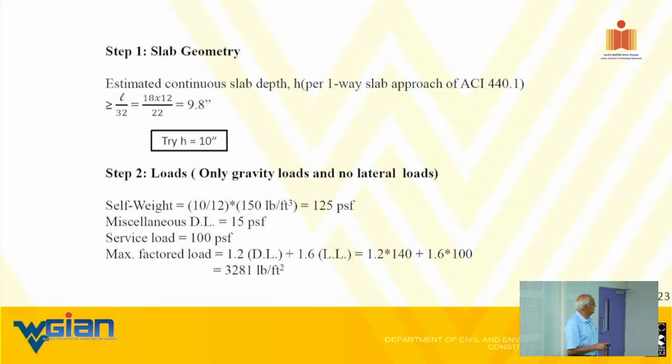The service load is given. Here is our very standard load combination. For only gravity load. Only for gravity load. Then you have to do all the other 5 load combinations as well as a check. Sir, we have already assumed that it's only for gravity loads. Yeah, but when I say the others, you may have a dynamic system. Still, it could be a gravity system, see? Or you may have the ice load combination.